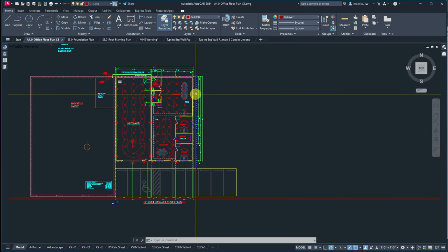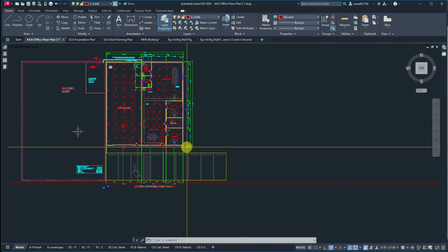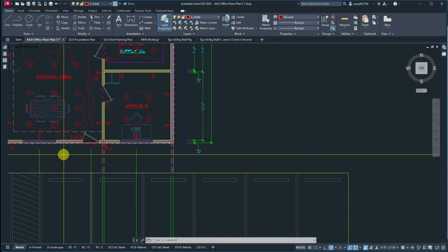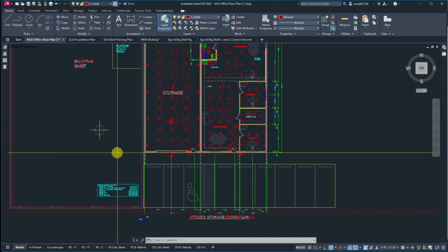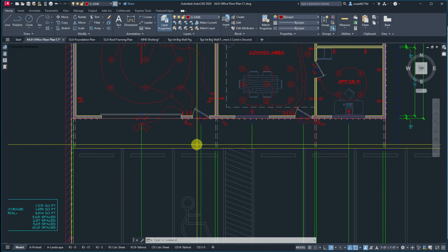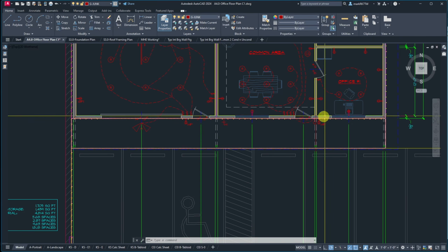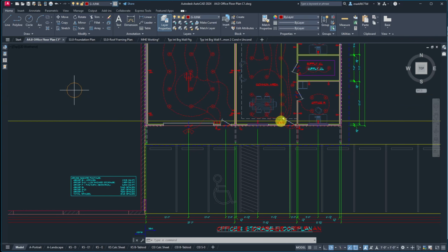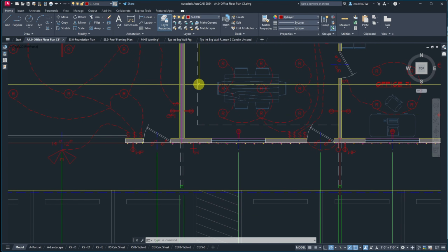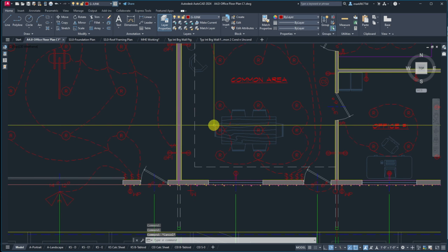Here it starts to shallow out, but then I get into my regular insulated wall, which is the detail you were just looking at. But on the front, I've got a concrete patio out here. So I'd like to draw a special detail that's going to allow me to do a horizontal insulation under concrete. And then I don't have to worry about burying it, and I don't have to worry about all of this. And if I've got my insulation like this dashed line here, that's not the insulation. That's actually for some duct work.